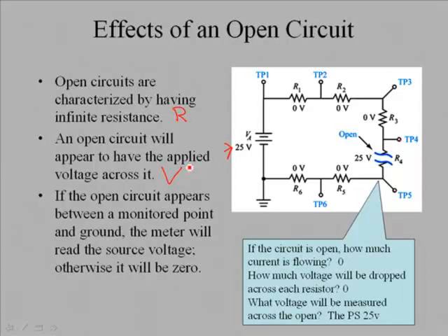Well, consider that when this circuit is operating correctly, we have current flowing through it. We have that loop, which is a requirement for all circuits. Now, when this component opens, we no longer have that loop. So there is no current flowing through these components, and you might notice the little 0 here on all these components indicating 0 volts.